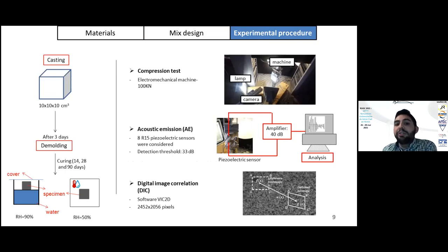Acoustic emission is the study of elastic waves generated by a material when it is exposed to external loads. Such waves come from friction and cracking sources. When a wave is initiated, it travels throughout the material to be captured by a piezoelectric sensor. The latter transforms the wave into an electrical signal to be studied or analyzed by the examiner.